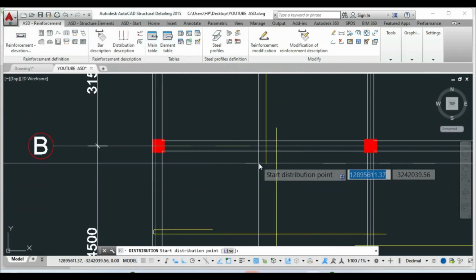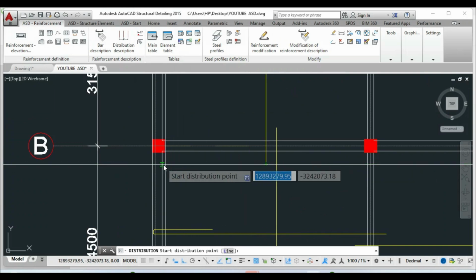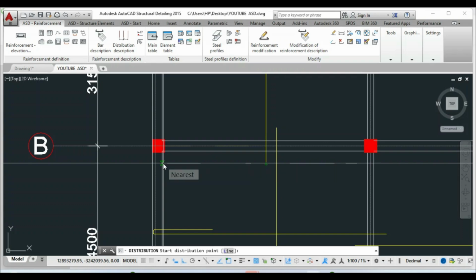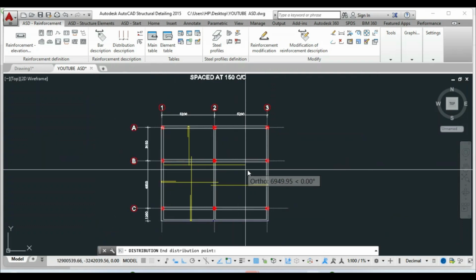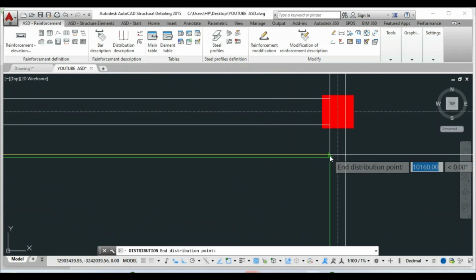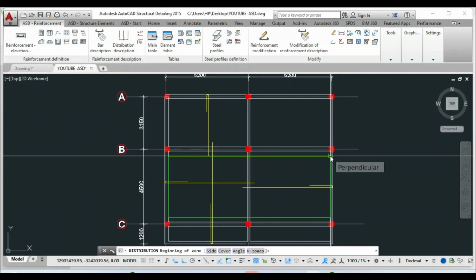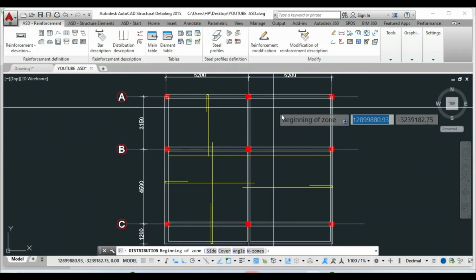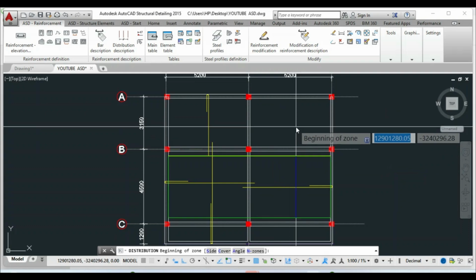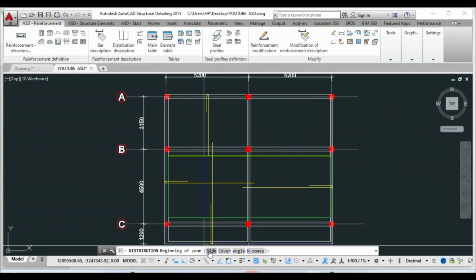And then you'd look at the edge of this, right? You click on it once. You click at the other edge where you want to distribute. You click on it once. And then when you realize that the highlighted area is down, but you want it up within grid line A and B, you click on side within the command menu here.